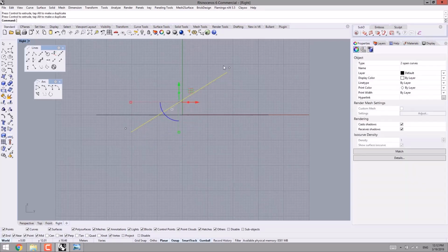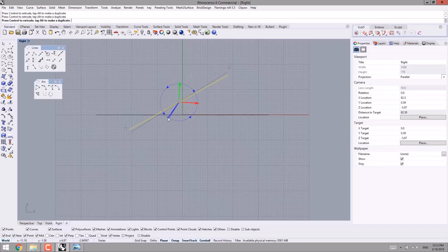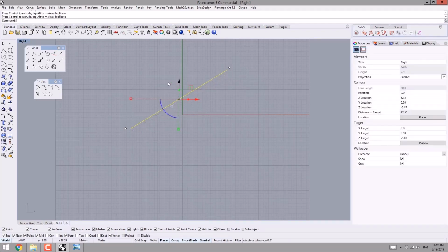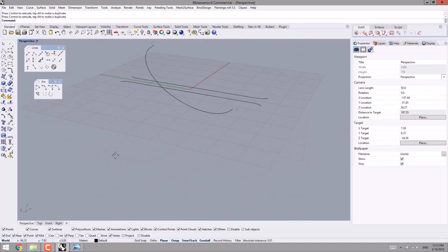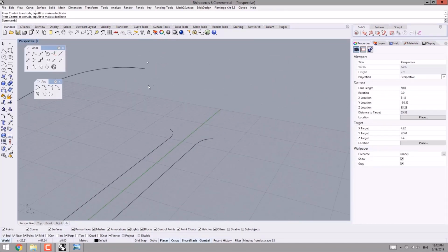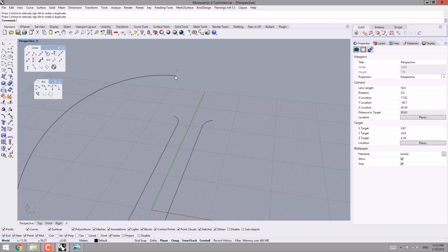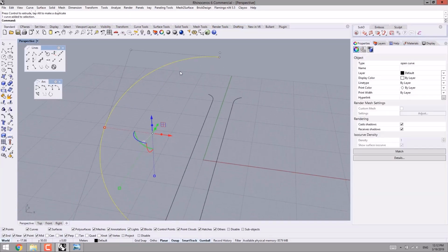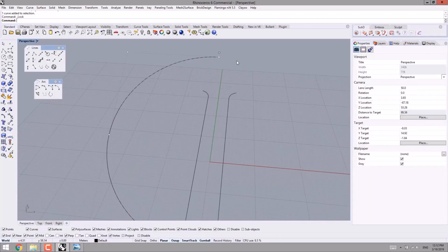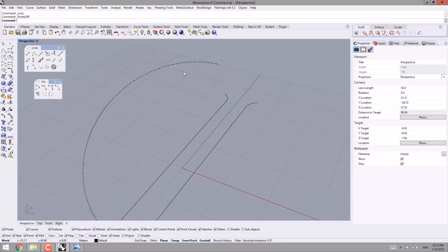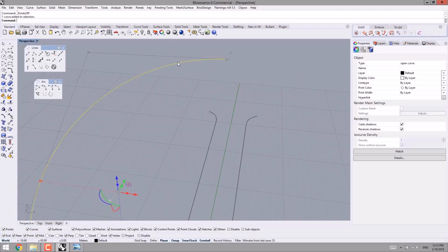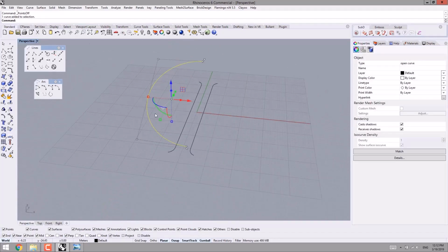Let me move it and adjust the position. As you can see, I'm adjusting the position based on the points that I have put based on the important image. Then we will have this arc. Here I select the greater line that I had, then by pressing Ctrl L, I lock this line, since I want it to be unselectable. As you can see, it is not selected.